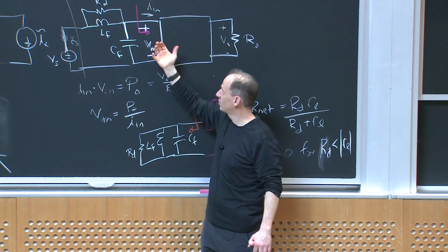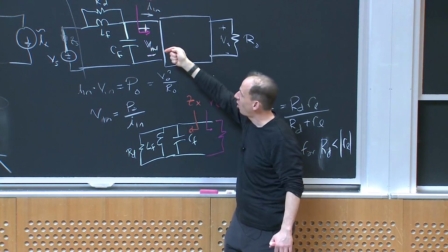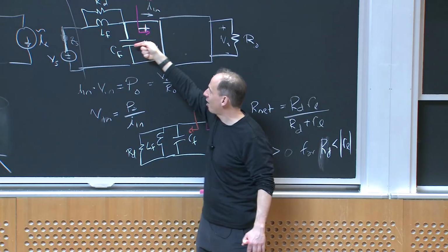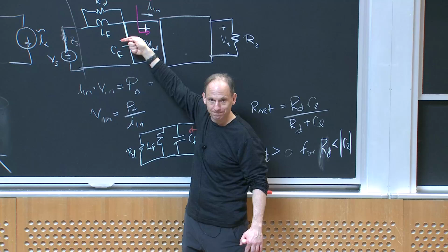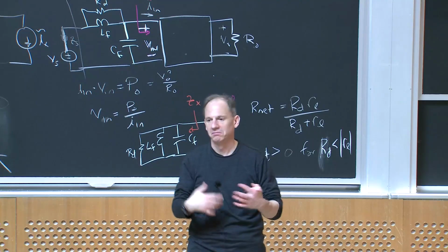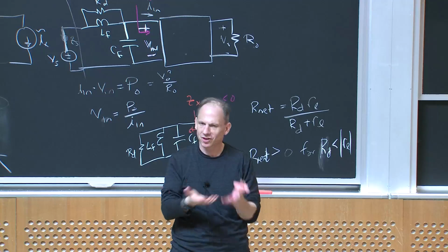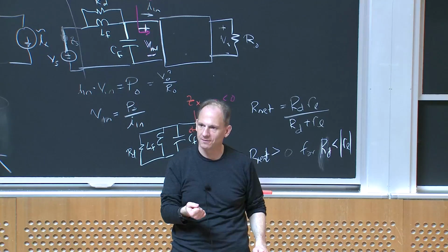At every frequency, that input impedance under fixed duty ratio ought to be smaller than the output impedance at the same frequency looking back into my output filter. If you put those two conditions together, you get a complete sufficient condition that you can ignore the effect of the input filter on the rest of your control design.